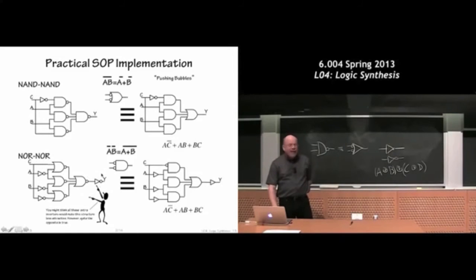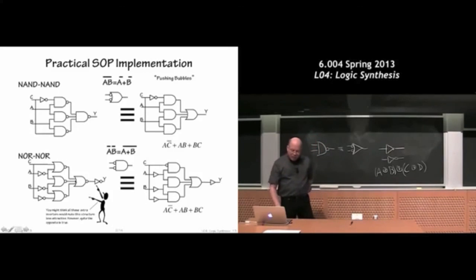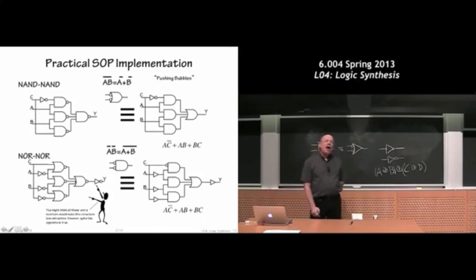So this idea of buffering a heavily loaded signal, a signal that goes to lots of other inputs, with an inverter is attractive because that way I can make that signal change more quickly by changing the dimensions of the single FETs of the inverter. And so this notion of buffering, here, it's a little easier to see. Here, A is connected to a pair of FETs. Over here, these inputs get connected to a lot of different signals. So buffering is something that is worth keeping in mind. So there are times when this slightly more complicated circuit would actually operate more quickly.